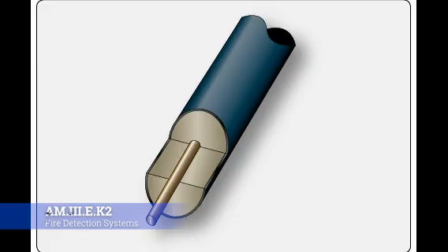Now that's really, really important because let's say you're flying along and you have a compressor stall and it blows up the engine. Well, as it blows up the engine, it sets off a fire in 2 or 3 different spots. Well, let's say in that explosion, it cuts the Fenwal detector in half. Well, it will still work as a detector sensing the fire elsewhere in the engine because it's set up as a loop, and so all of a sudden, you can lose half of the Fenwal detector, and it'll still go off. Then let's say that they pull the fire bottles, put everything out, and they think, "Woo, we avoided the fire."